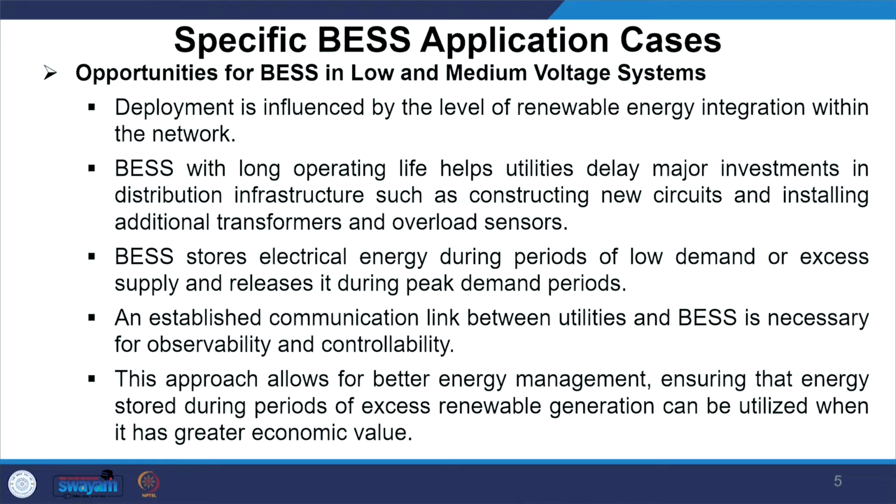Let's say your transformer is currently catering X MVA to the consumers, and tomorrow more customers are connected to your distribution system, which is, let us assume, a 10% increase, which is 1.1 times X. The transformer would need to be replaced by a new transformer of 2X capacity, which is very, very expensive.